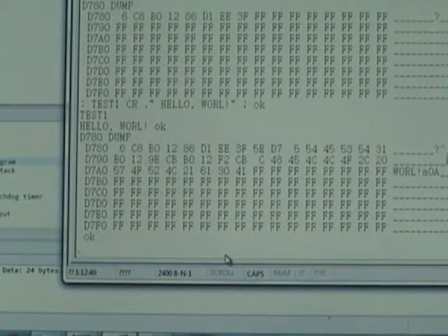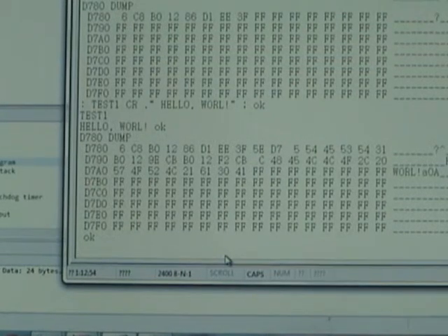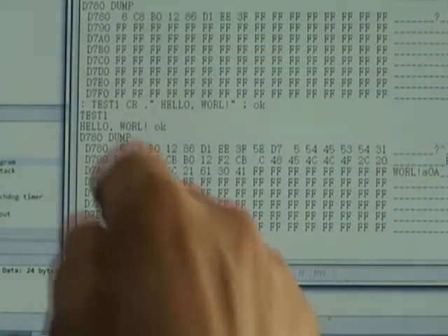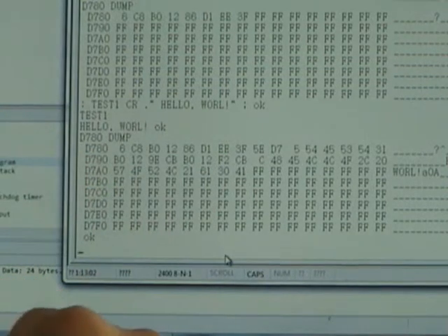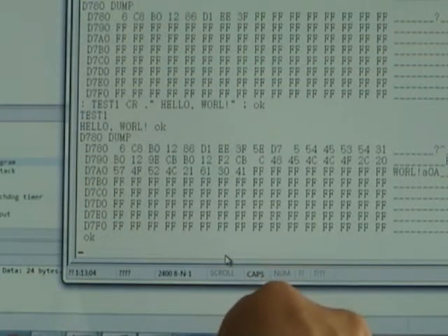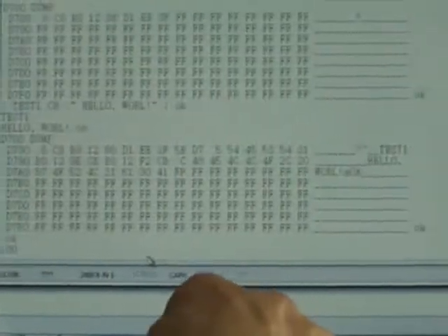And when you don't have any memory to work with, then reload the eForth system. So you debug your code, and then the next time you load first only the verified code, and then from there you can go on doing some more work.